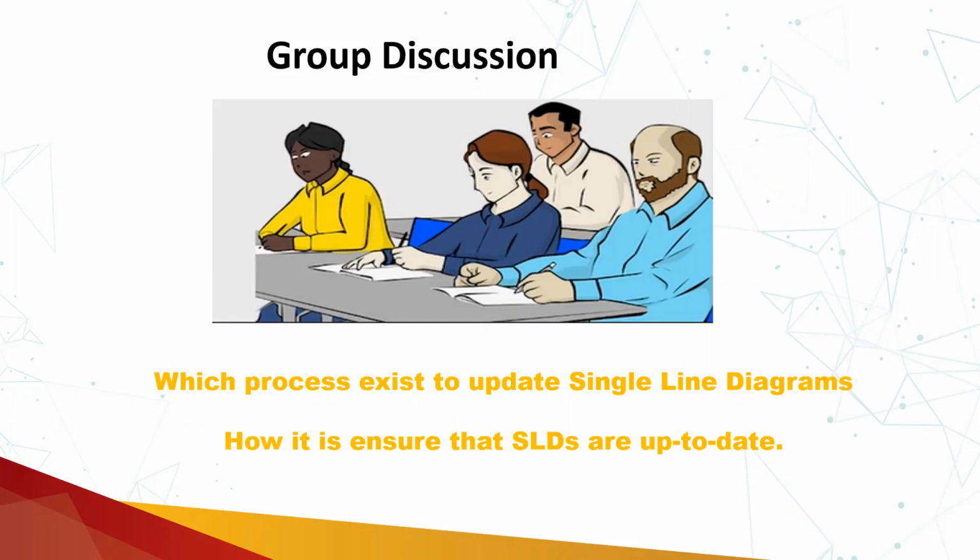On the other hand, if the single line diagram is updated, then the information will be available on the SLD that in order to create an electrically safe condition in substation B, you have to switch off the outgoing from substation C, from the cable which is feeding from substation C to substation B. So the quicker you are updating those single line diagrams, the more that will mitigate the risk of wrong operations, and there will be fewer chances of any incidents happening.